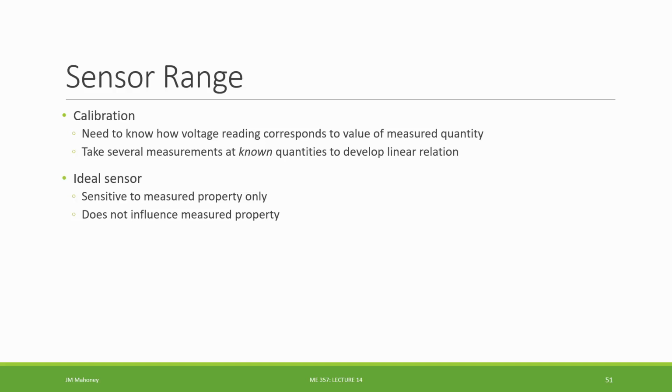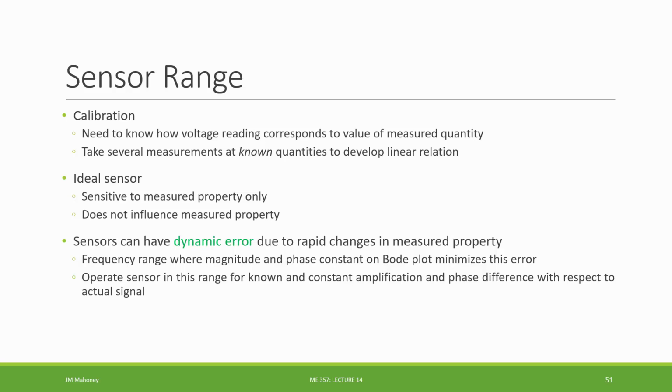And back to talking about sensors and how they are measuring the desired quantity, a sensor is going to have this dynamic error when the property we're trying to measure is changing quickly. So going back and talking about the calibration, again, typically we are immersing it for a while at 0 degrees, immersing it for a while at 100 degrees in the case of the thermocouple, but we might be measuring some liquid whose temperature is changing relatively rapidly. So this is now putting into the thermocouple or into our sensor a dynamically changing property.